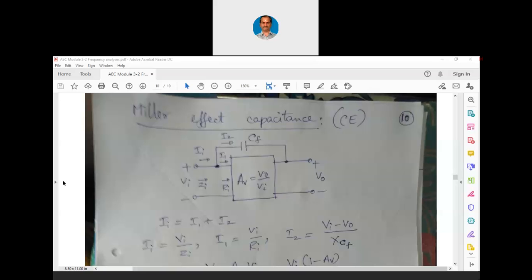But now, when there is a parasitic capacitance between base and collector, it is going to affect the switching of the transistor itself, because instead of causing a change in the base current, the signal may get directly coupled to the collector by means of this internal capacitance. That way the transistor may not switch properly at all when the input is of very high frequency.